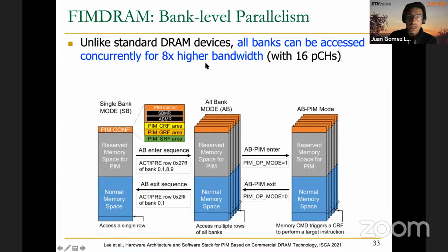And the reason is that in order to get access to the data, we have to send 2 consecutive read or write commands to each of the banks, right? And the standard imposes twice the latency when we perform 2 consecutive accesses to the same bank. It's twice the latency than if we issue accesses to different banks.